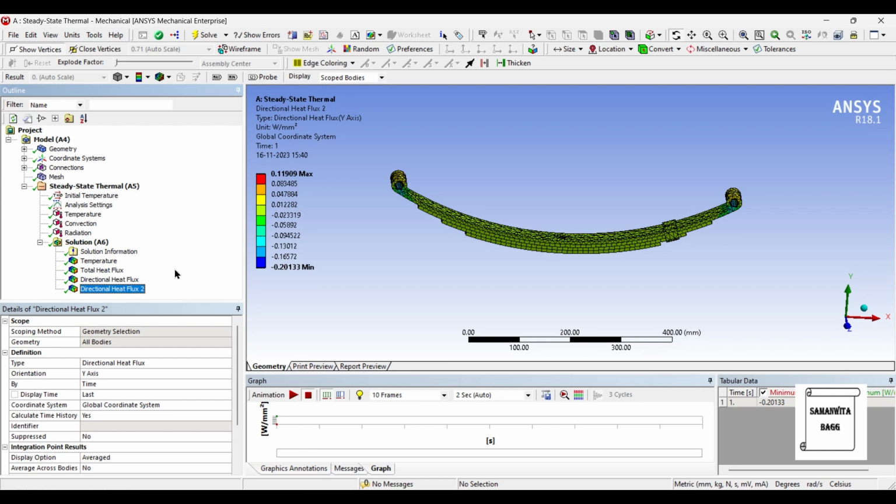It is not specific to a specific object. For example, the leaf spring will not be made only of steel. It can be made of various other materials. Now in this, one more aspect is the composite materials which are being used for the leaf spring. In fact, the leaves can be made of different composite materials also. For example, epoxy carbon, you can have glass fibers. So these are the materials which are also used in these cases so that the heat loss is more, it is light in weight, and it is going to have good life with the use of composite material.